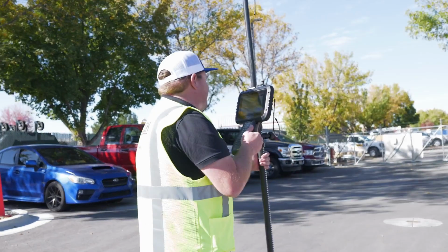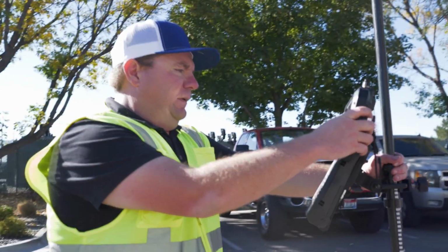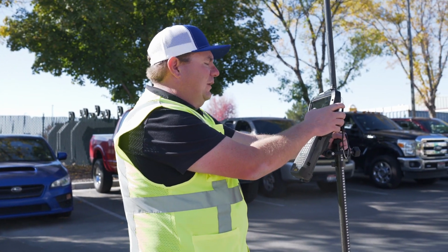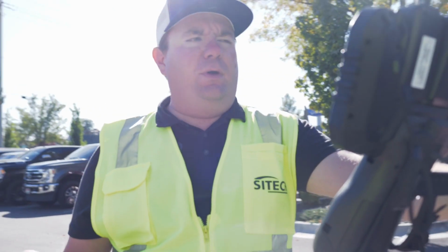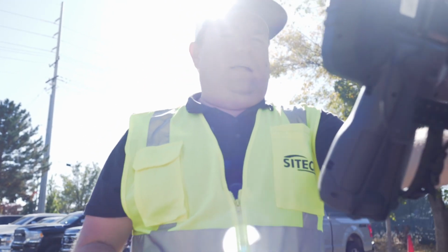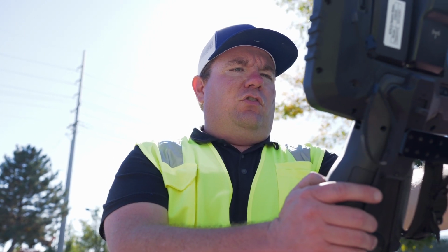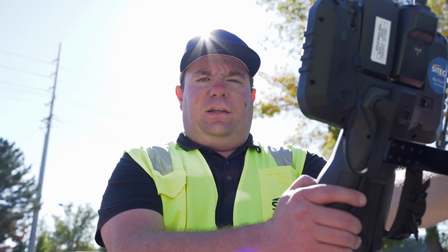And then we'll just shoot this last water valve. We're going to do the same thing when shooting duplicate points. You don't have to name every point individually. It'll automatically relabel the point as water 1, and then water 2, water 3, and so on. So we can quickly just go shoot our second point. And that's how to shoot a feature point in Trimble Siteworks.